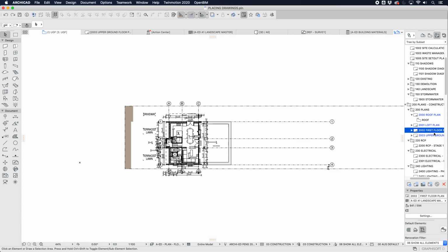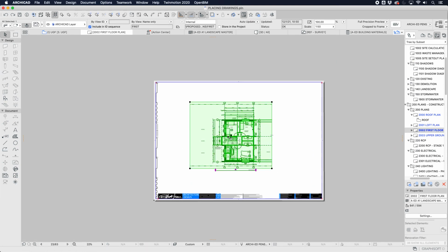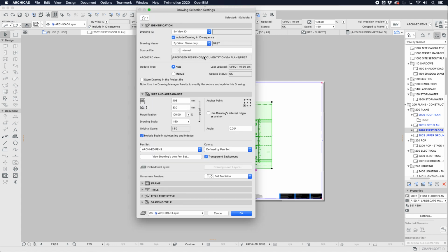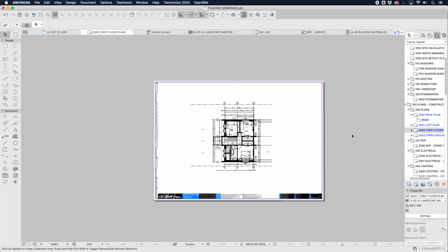So when we go back to here, we don't really want to change the scale. We can change the scale if we want to for magnification purposes, only maybe for presentation. I wouldn't do this for technical documentation because it's going to mess with our scale representation of text, and we don't want to do things like that. Hopefully that's answered all your questions.